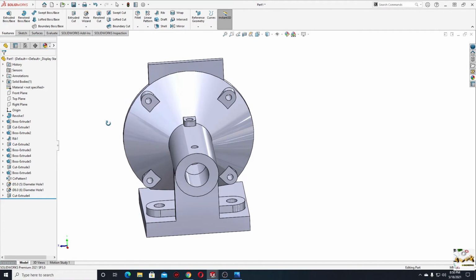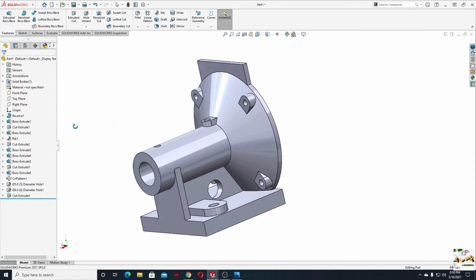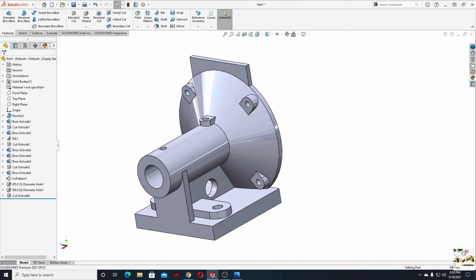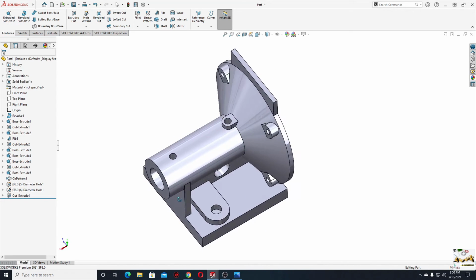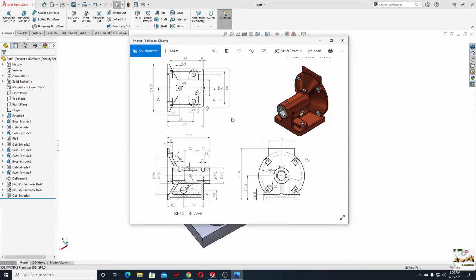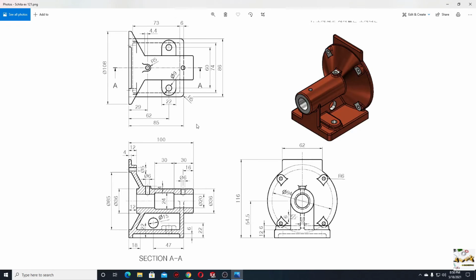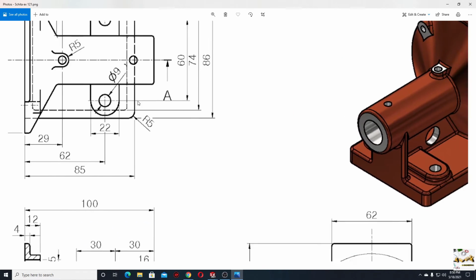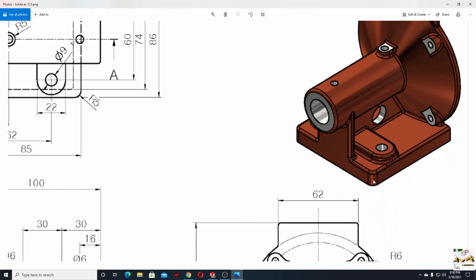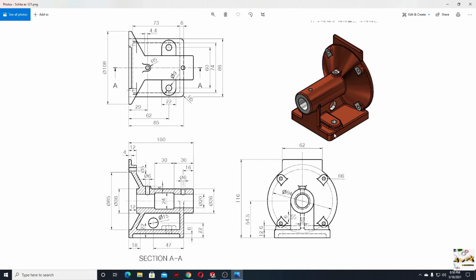Nice, and now we have to apply some fillets because we made everything here. So let's see. We can see here a fillet with radius 5, which will be applied to these 4 edges at this rectangle, and then for the other fillets we're gonna use radius 2.